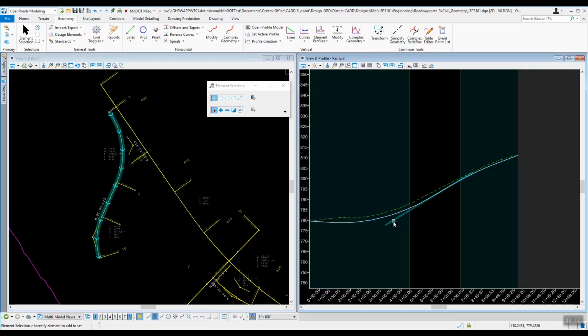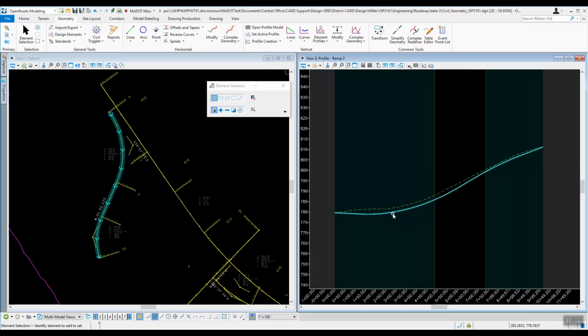If you want to double check everything is correct, you can left click on it and you can see you've got the negative 0.5. You've got an elevation here of 803 that we were given, station 3 plus 70, station 7 plus 95, and then a snap to the end. That's method one of the rough draft, if you wanted to do the rough draft version.